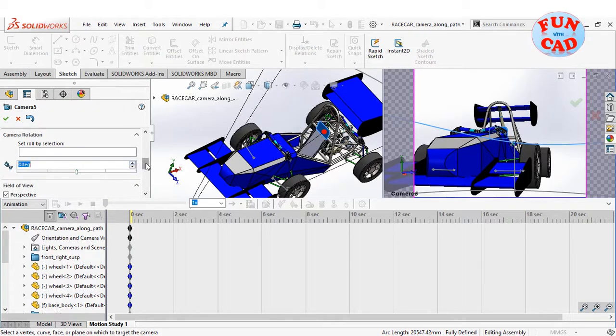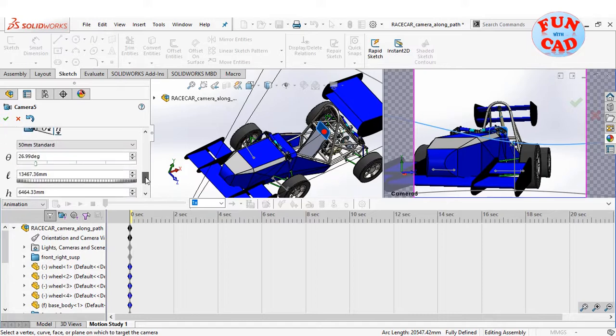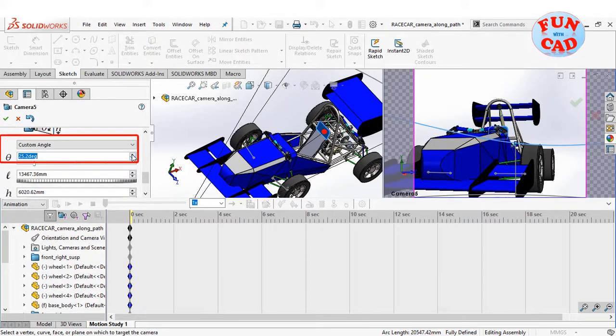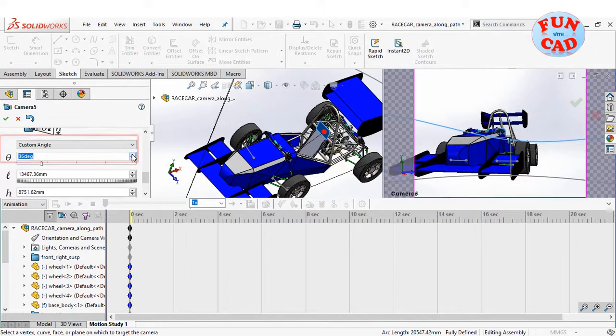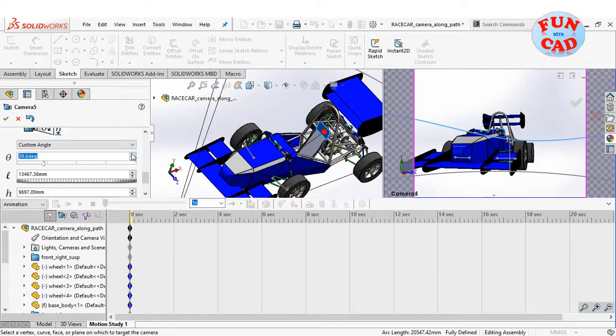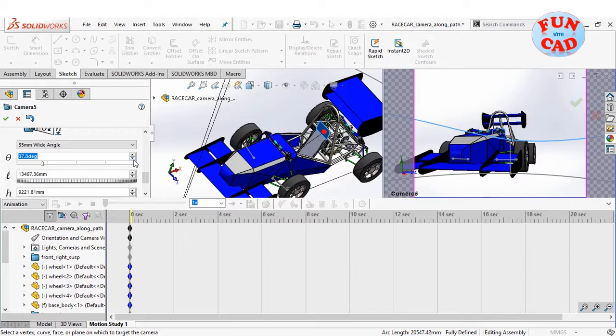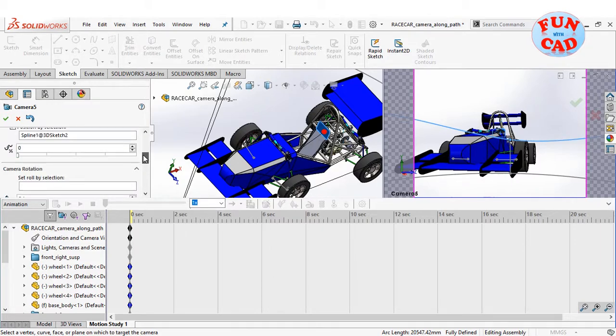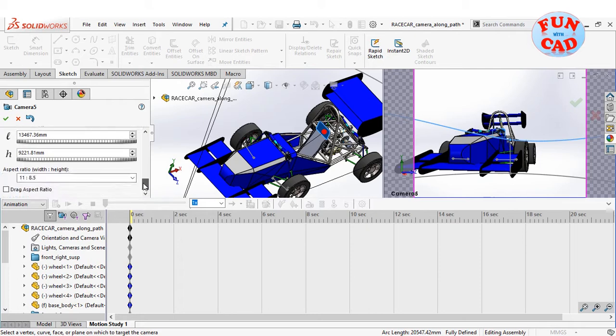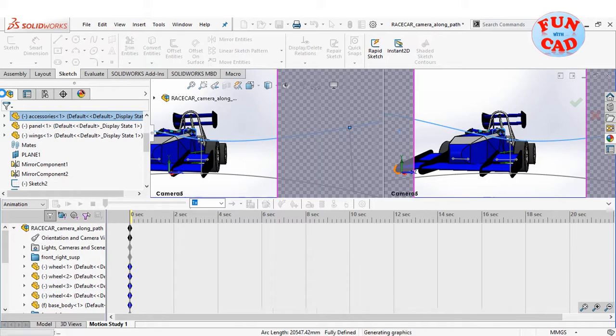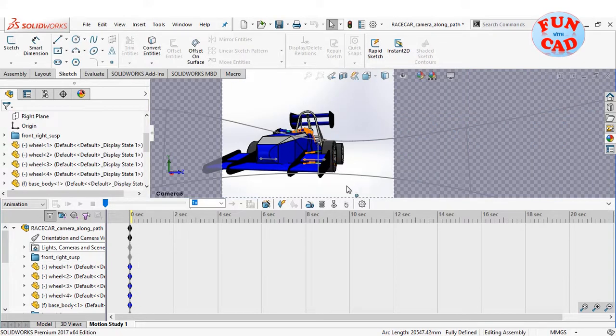Turning the camera roll, to adjust the view. Now, adjusting the angle to zoom in or zoom out of the car as per the required view. No other parameters need to be edited. Click on OK. Now we have the first view of the animation. Now, we decide at which time we want the next milestone of our animation, and drag the time to that time.